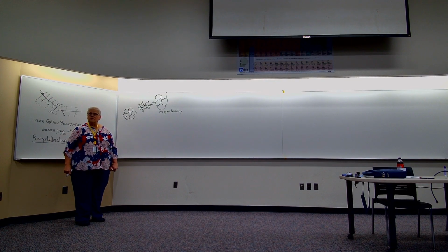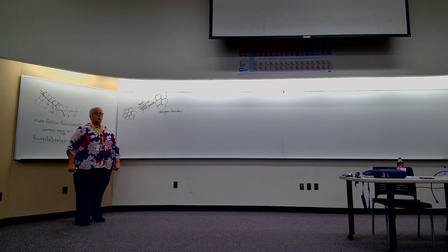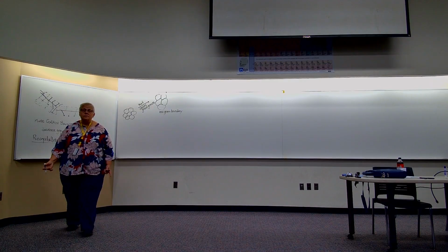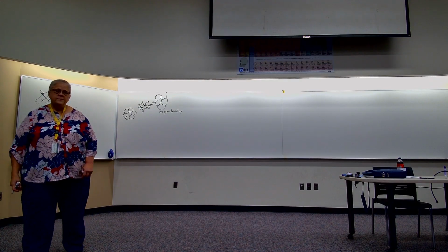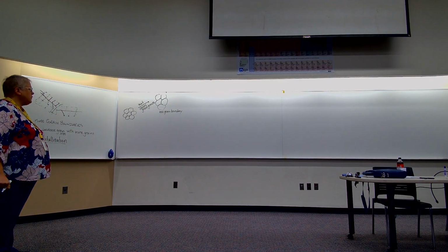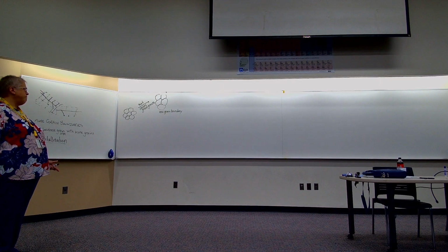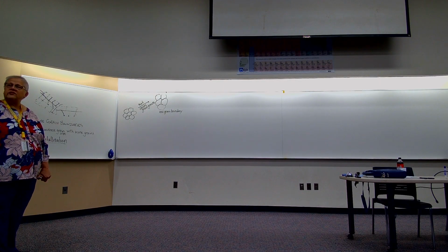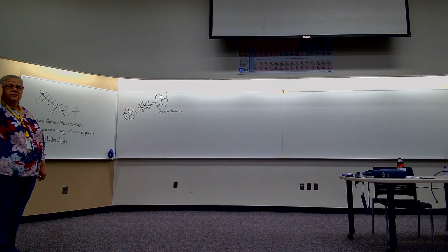Brittle? What was that? Brittle? Where did that come from? Yeah, what did you say? Brittle? No, making it brittle is deforming. If anything, we're making it softer. And you'll see that in a second. So if we just heat, we have less grain boundaries, it's softer. This is a process called annealing.